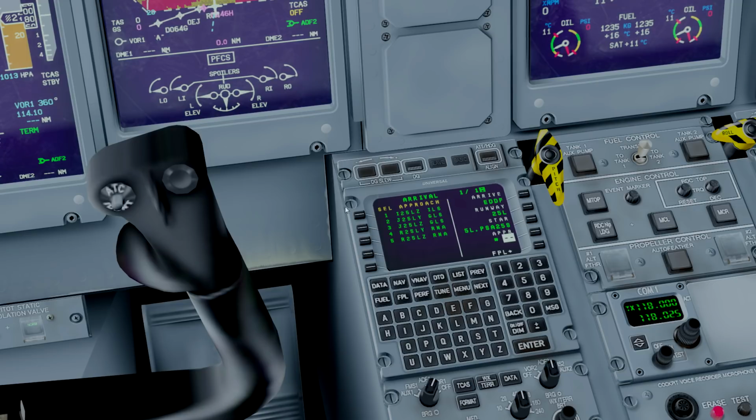And here you can also indicate what type of approach you're going to be flying. So we'll just pick the ILS Zulu for runway 25 left, number 1. As you can see, it's actually a pretty convenient way. It's just the method of presentation of the information is different. The method of entering all the information is different, but it works.